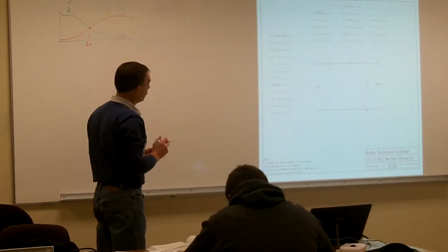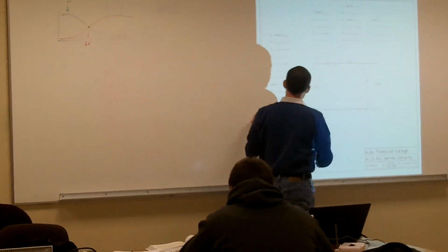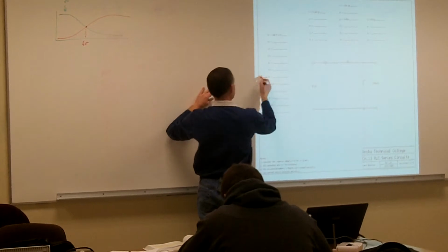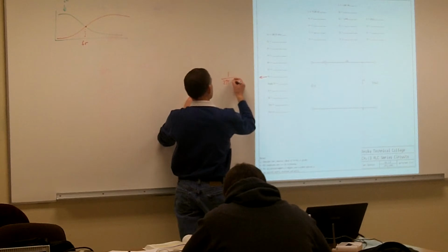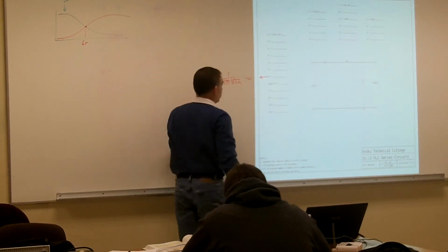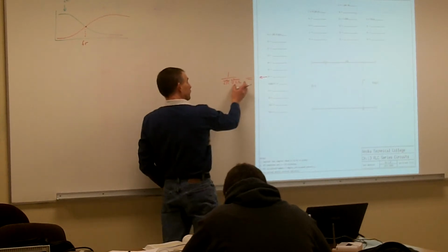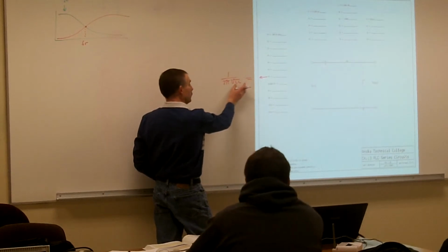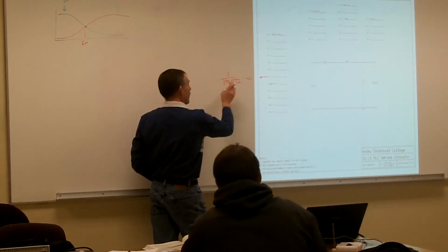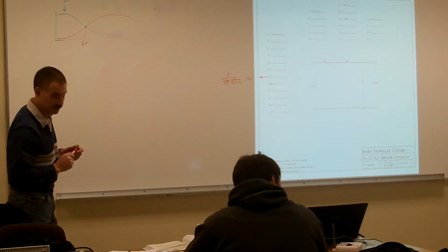So the first thing we want to do is find out our resonating frequency for our particular circuit. To calculate your resonating frequency, it is equal to 1 over 2 pi times the square root of L times C. That will equal your resonating frequency. So what I do is I take my inductance and my capacitance, multiply those two together, take the square root, multiply it by pi, multiply it by 2, and then hit my inverse key. That gives me my resonating frequency.